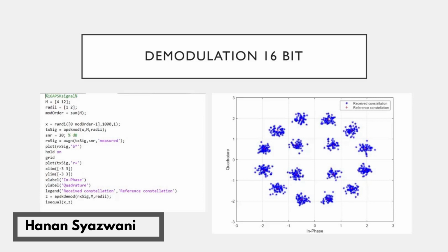As a result, the constellation collapses towards the outer ring, and this is due to the AM/PM characteristic. Moreover, the outer ring is phase shifted with respect to the inner ring because of the AM/PM distortion, and the performance can be severely degraded.